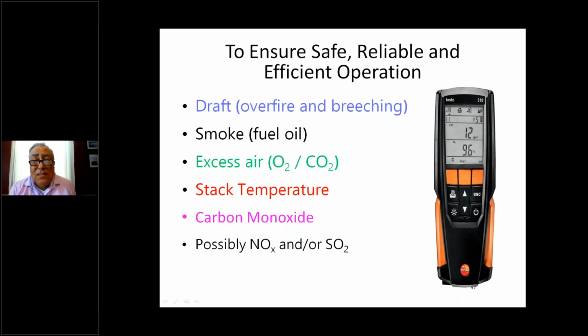And to go the other way would be to remove air, obviously, right? Well, yes, if you remove air, obviously we're trying to get as efficient as possible. By lowering the excess air, and keeping within the parameters that we're looking for, our efficiency goes up. But again, there are some cases where you just can be too efficient, and I'm really talking about fuel oil. That's because you still don't want to condense fuel in your chimney. Now, if we're talking about condensing gas equipment, well, that's okay. We want it to condense. There you go.